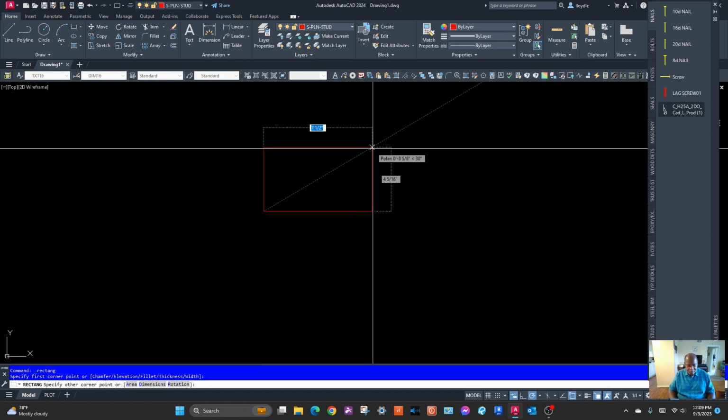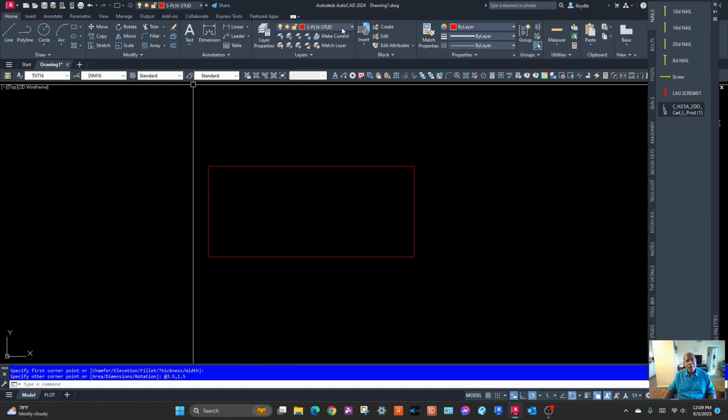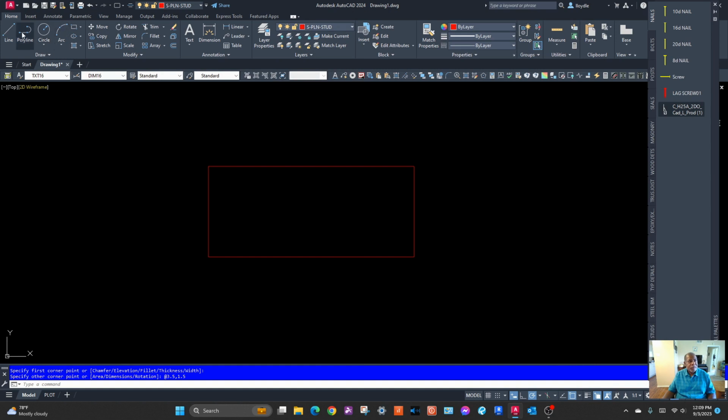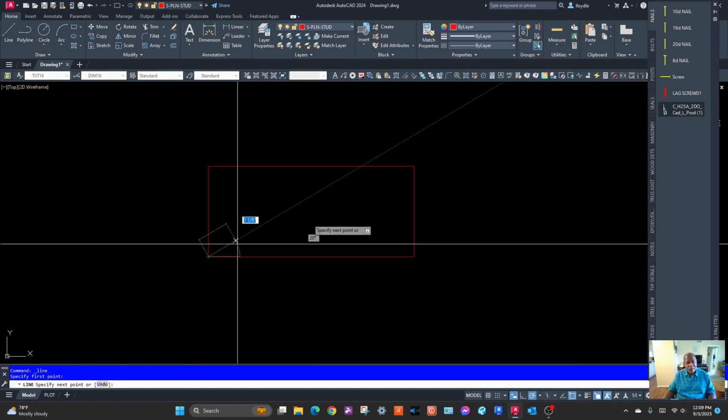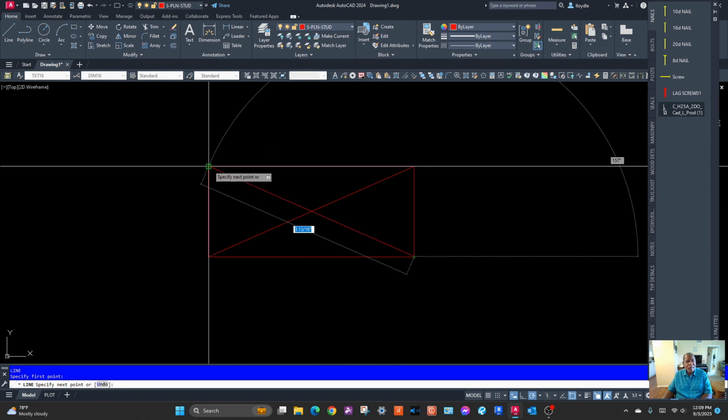And, okay, 2x4 studs. So I go at symbol, it's going to be 2x4, that's 3.5, comma 1.5. That's the actual size of a 2x4. Now, okay, I'll just keep that on. Let me draw this. Need to X in here, X in there.